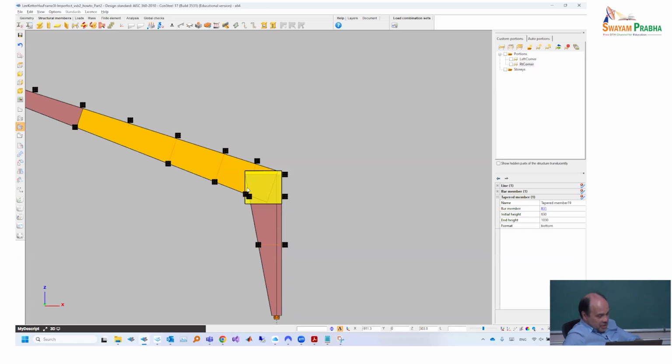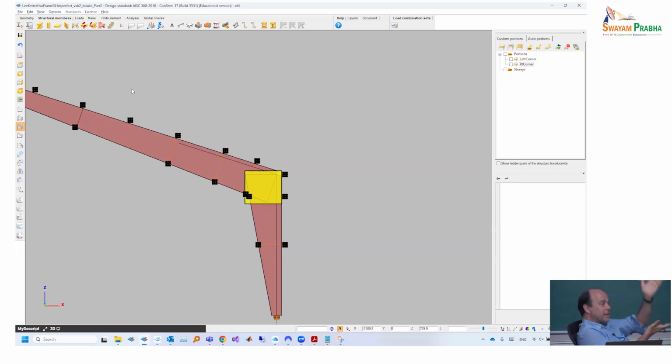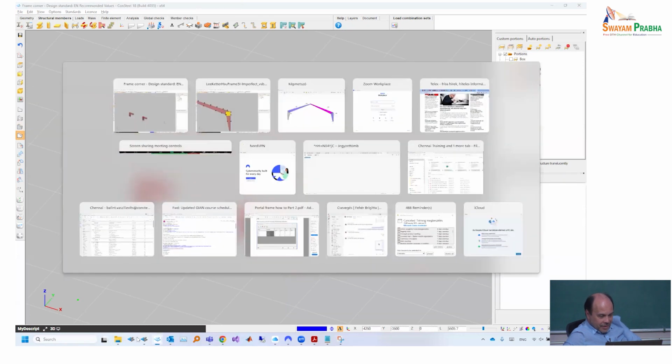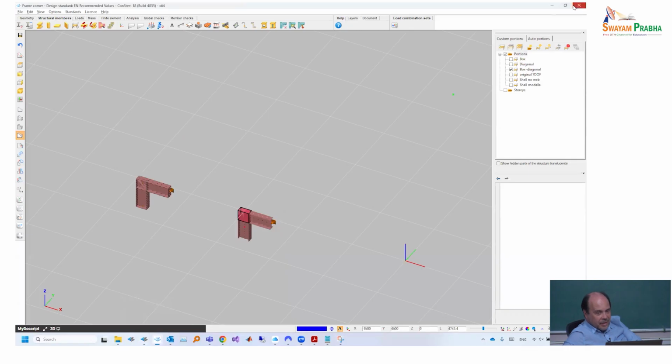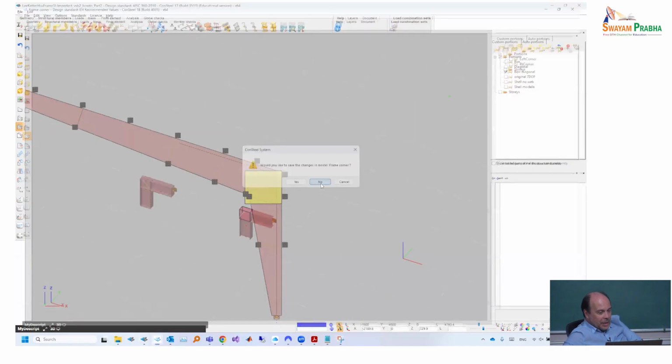So because of this, in the original model, where Professor White said that he expects overstress in the rafter only, he artificially increased the beam depth the way that they will exactly reach the reduced expected size at the boundary of the column. So that's why it's another geometry calculation, but you can figure out what depth you need where the column and the beam intersect to get 1,000 depth.